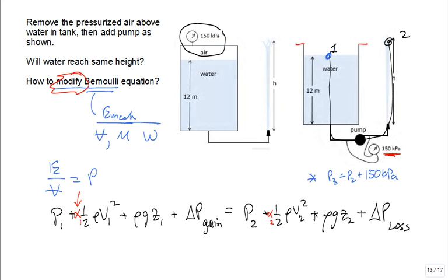Looking back at this problem, where do you think there might be some losses in the real system to make it a little more accurate so that we don't just have the maximum height? We'll never get the maximum because there's really some friction and other losses in the system. Where would we look? Probably right in here on this inlet. Probably along the length of a small diameter tube or pipe or fitting. Probably somewhere like that nozzle. If we have a bend or a 90-degree elbow, that's where we would have some adjustments for actual losses to be closer to the real system.